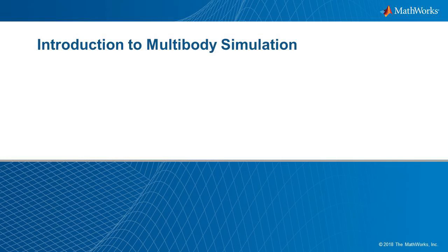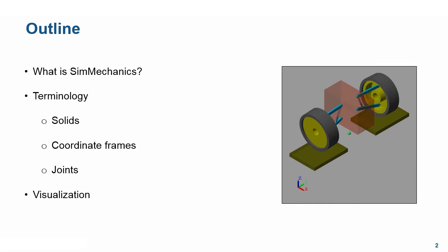In this video, we are going to introduce the concept of multi-body modeling with SimMechanics. Specifically, we will talk about what SimMechanics is, terminology used in SimMechanics and multi-body modeling such as solids, coordinate frames, and joints, and finally, how to visualize multi-body components.